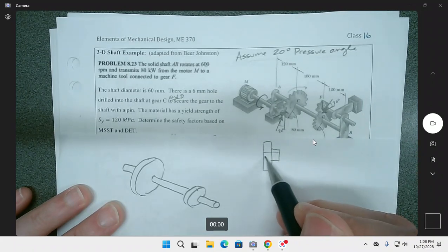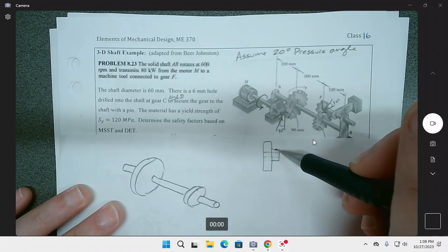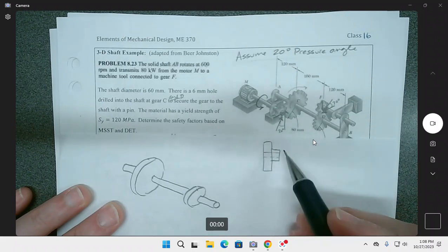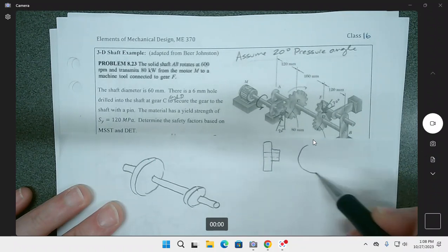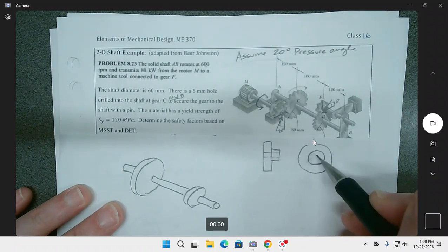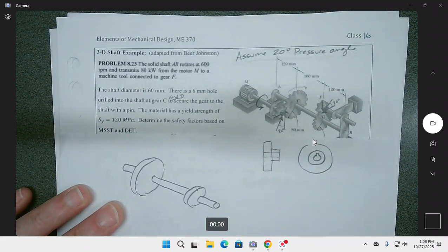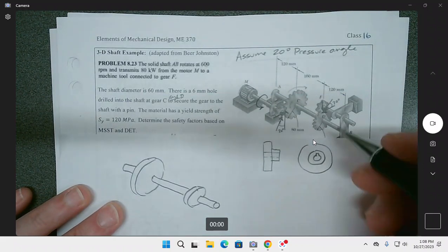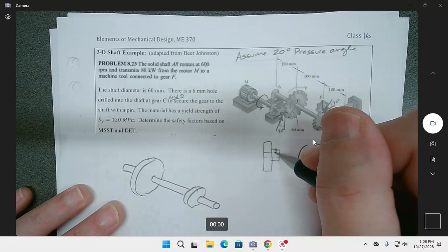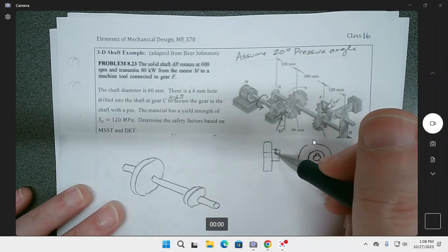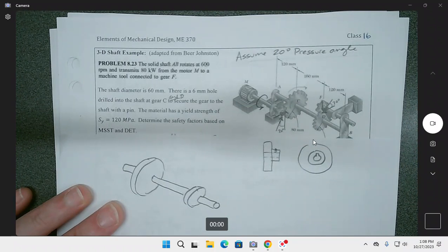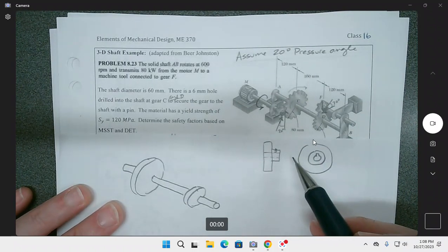So the shaft comes through here in this hub, and quite often, the most common way, is to have a keyway in there. You have a little rectangular piece, a little key, that fits into there, and then there'll be a set screw that pushes down onto that. It does a pretty good job of keeping it in place along the axis of the shaft.